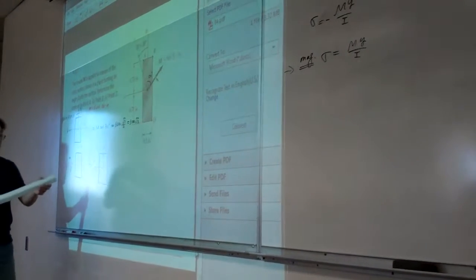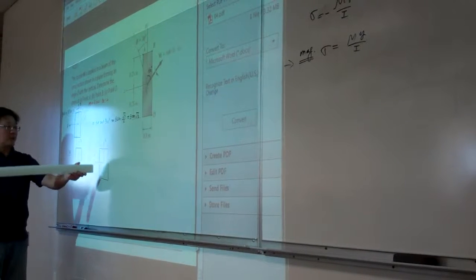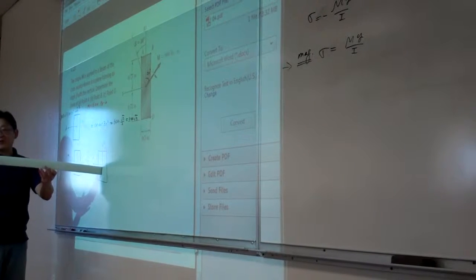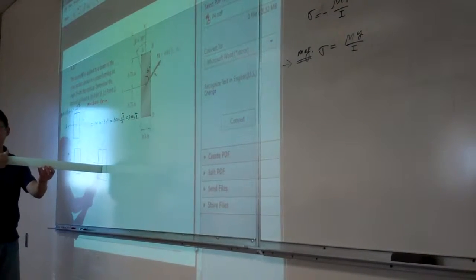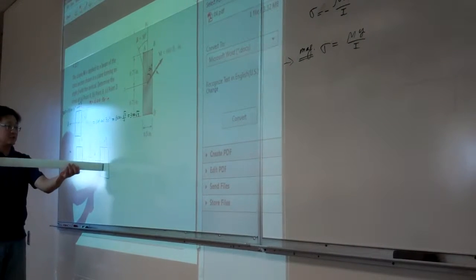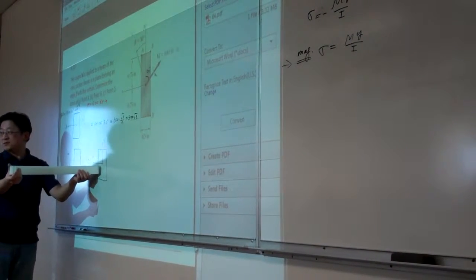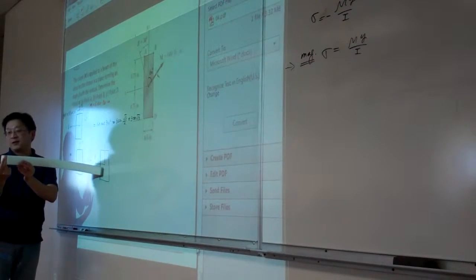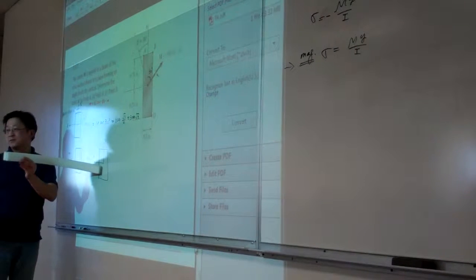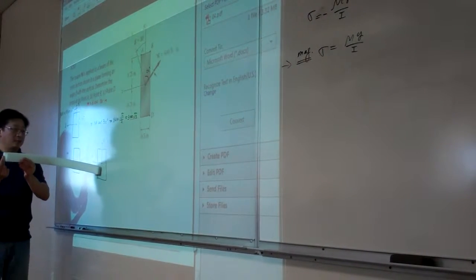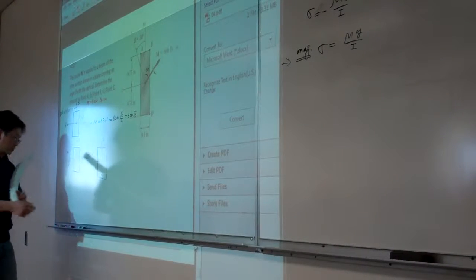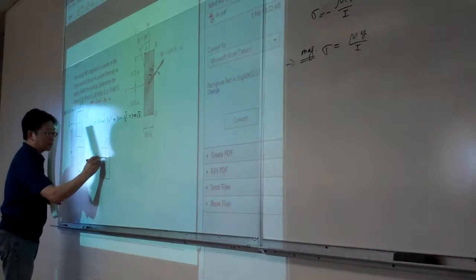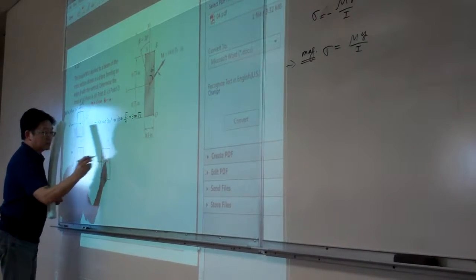And now for this case, again, the bending My is like this. So now this is a cross section. Bending on this side is bent like this. So for this scenario, the beam will be bent like this. And now you can see in this way, which side, right and left, which side is in tension? This one. Okay. This one, the right side in tension. So, sorry, left side. Sorry. And then this is in compression.